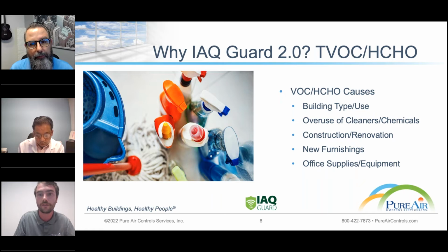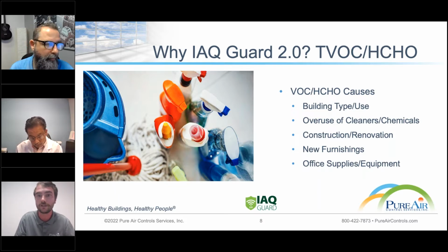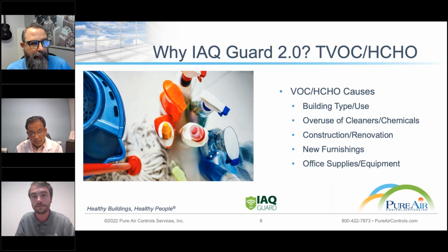You're bringing in a lot of contaminants, drywall, paints, sealants of that nature. All these things can compromise human health as they're carcinogens. So we want to make sure that if you're having something done like this, you can keep a really close eye on it in a particular way, around the clock monitoring, and then after the fact, make sure that you return to a baseline normal indoor air quality, and you're not continuing to affect your occupancy's health.